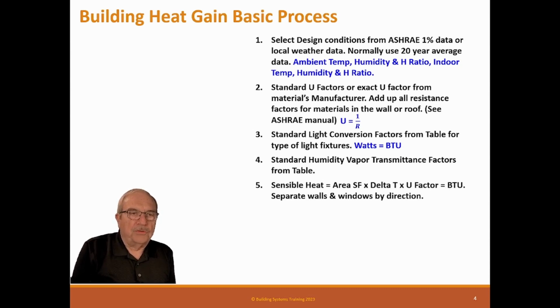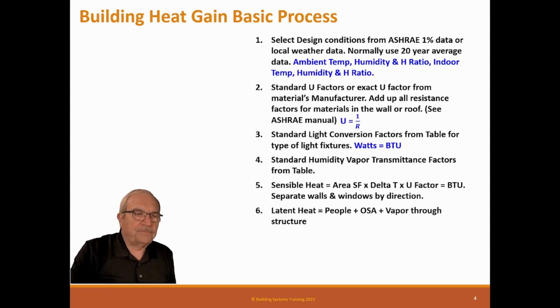Separate walls and windows by direction. So you want to have one of these heat gains for the south, the north, the east, and the west. And then also what you want to do is calculate the latent heat, which is people plus the outside air plus vapor through the structure. And also on the sensible load, you want to calculate